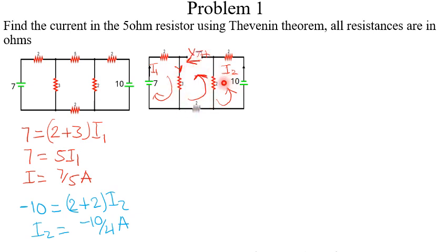We realize that when current starts to flow, I1 comes here and I2 also comes here, but this 2 ohm resistor, no current will pass through it, because the current doesn't split since there's an open circuit here, it just passes all the way back. So these 2 ohms wouldn't receive any current.